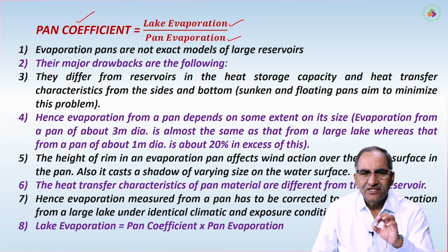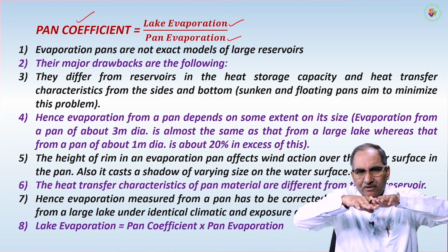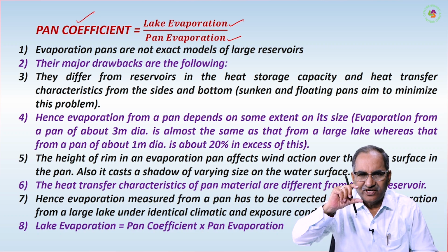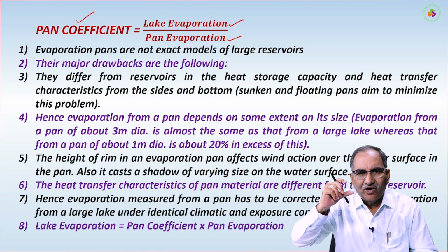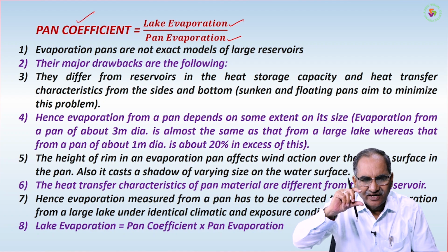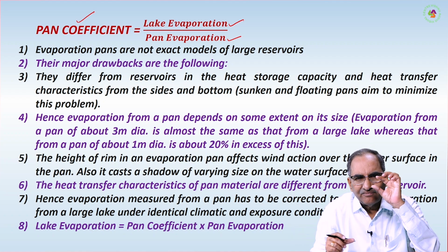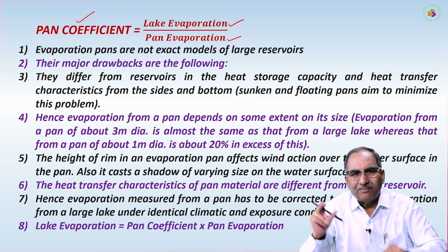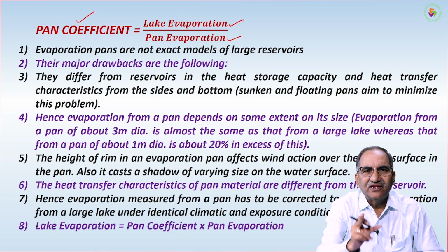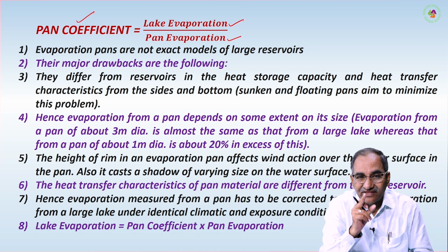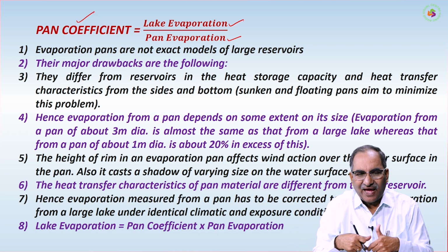The principle is we pour water to a fixed level, and measure the depth of water actually. Now next day morning we come and again we measure the depth of water. Whatever that level has decreased, that we measure. This much mm per day decrease has occurred. That much mm per day is the evaporation. From where is that evaporation? From that pan actually.